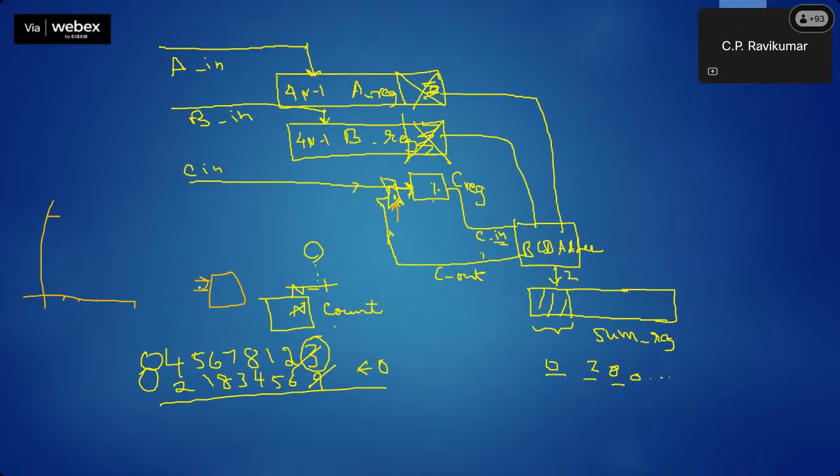When reset is high, it will set this mux to 1. When reset is low, it will change this to load from here, and the count has to be decremented every time. So you can design that control unit. It will be very simple because only very little has to be controlled. It's basically the reset signal itself acting as a controller.